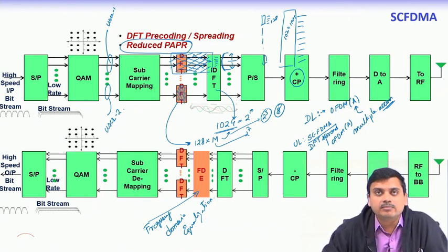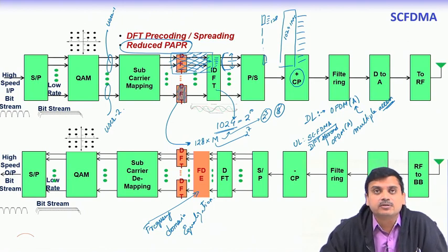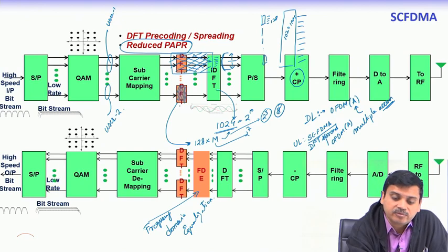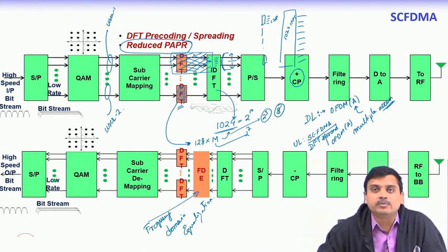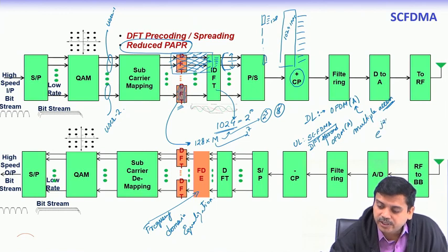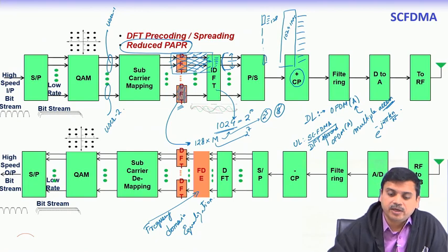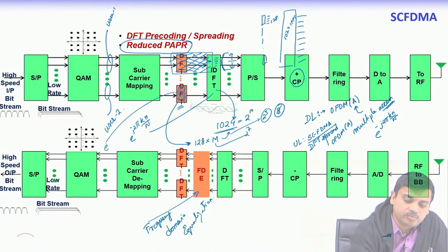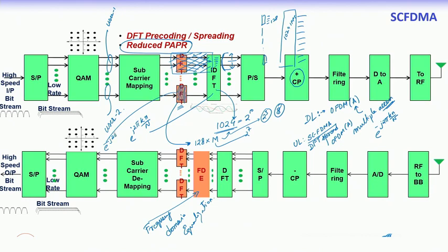Okay. So, that means this particular operation is as if it is doing a spreading operation on top of the DFT or the IDFT operation. So, this is called a DFT spread OFDM, and the spreading codes are derived from the DFT matrix, e to the power of j. The DFT matrix gives you e to the power of j 2 pi k n upon n, and here you will be getting e to the power of minus j 2 pi k n upon m.